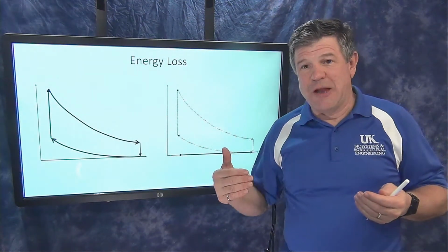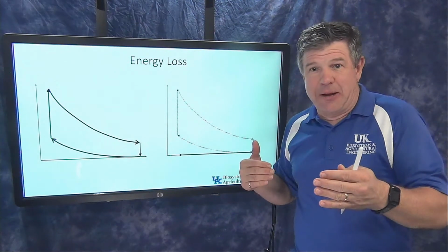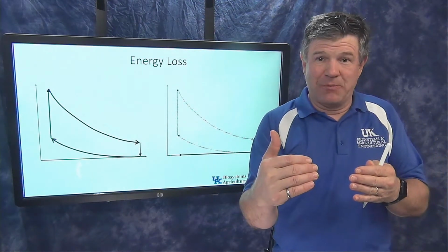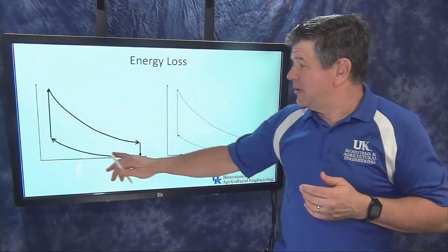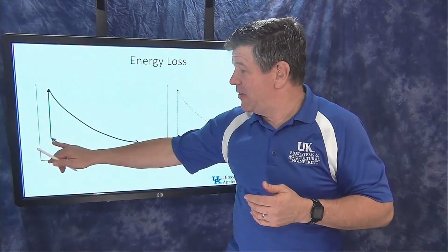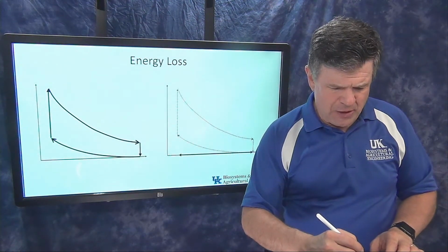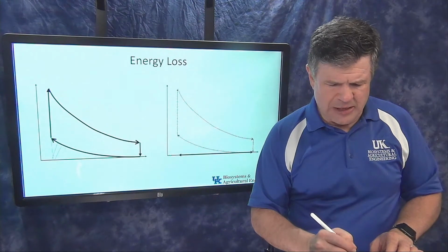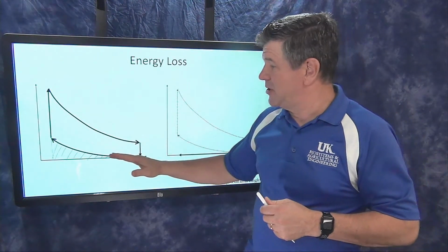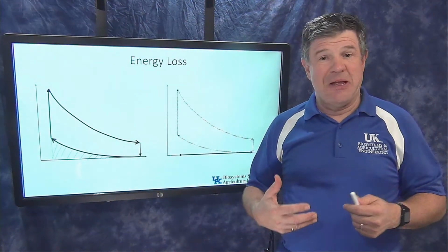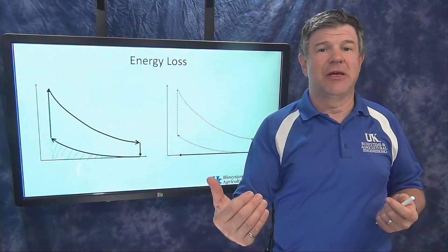I have to push that piston up, and I have to compress those gases. So that compression, to get those pressures up to where I want to ignite that fuel, that takes energy. Now, what does that look like on this graph? That's anything underneath this lower curve. So if I drew a line down here, crosshatch this area, this is energy lost. So that's energy that is not going out for useful work. I have to have that to compress the gas to make the engine work.